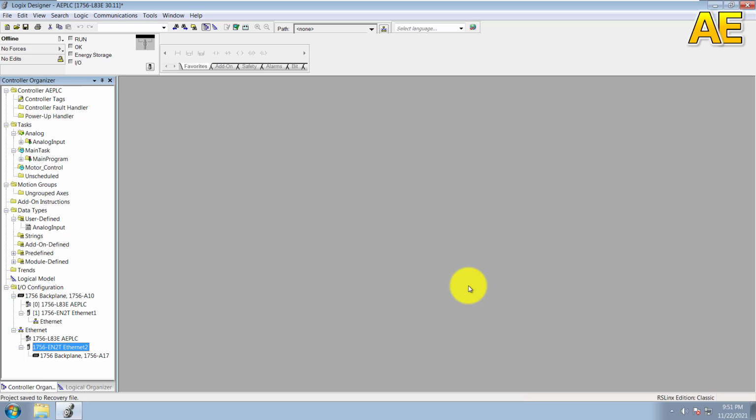If the module is in the remote chassis and the chassis has analog modules, diagnostic digital modules, few output modules, or multiple communication modules, then we don't need rack optimization. If the module is in the local chassis, we don't need rack optimization.